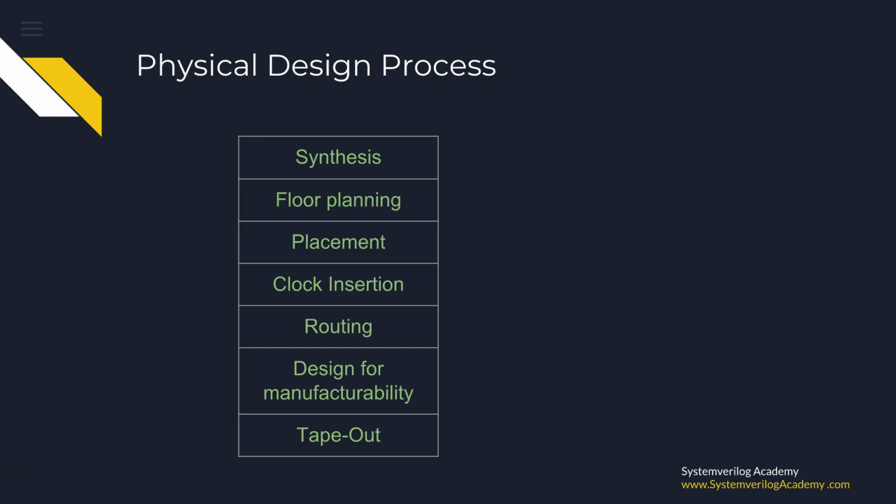The last phase in the physical design process is tape-out and mask generation. After doing a lot of iterations in the above steps, with utmost care, the design data will be ready, and it needs to be converted into photomasks in this phase. The final photomask will be generated and sent to the manufacturing foundry to produce the IC on silicon. This is called tape-out, as magnetic tapes were used to write this photomask in early days.